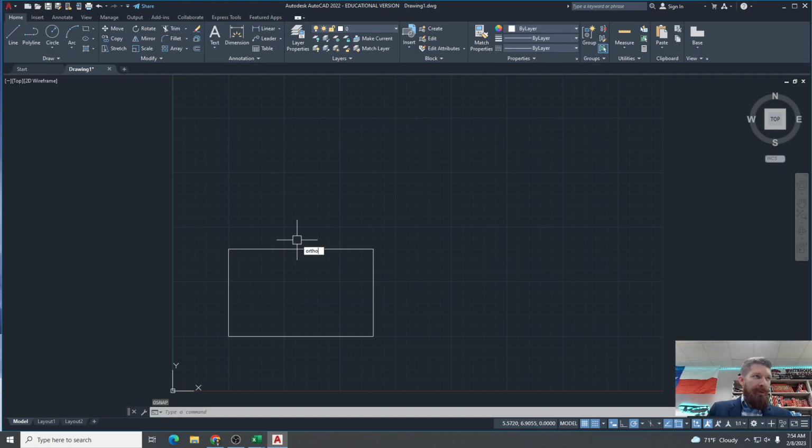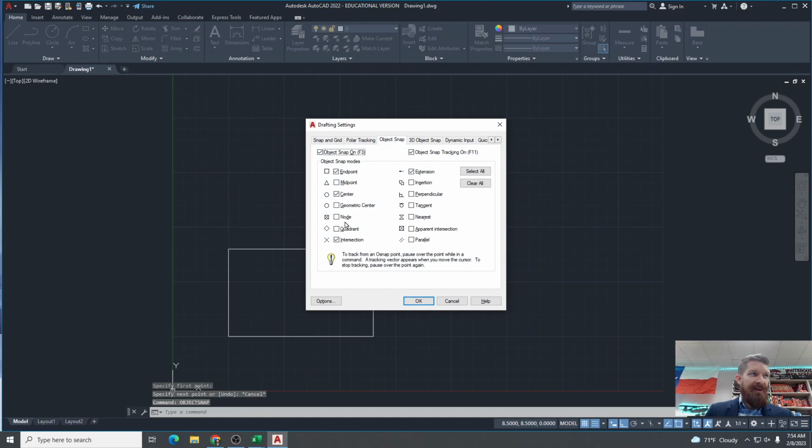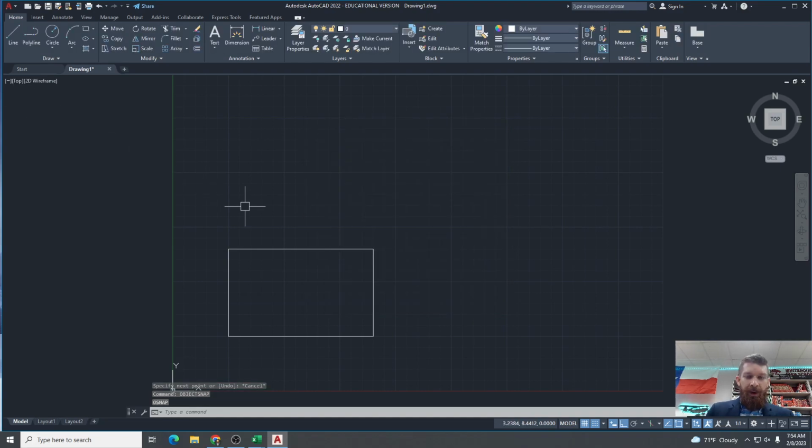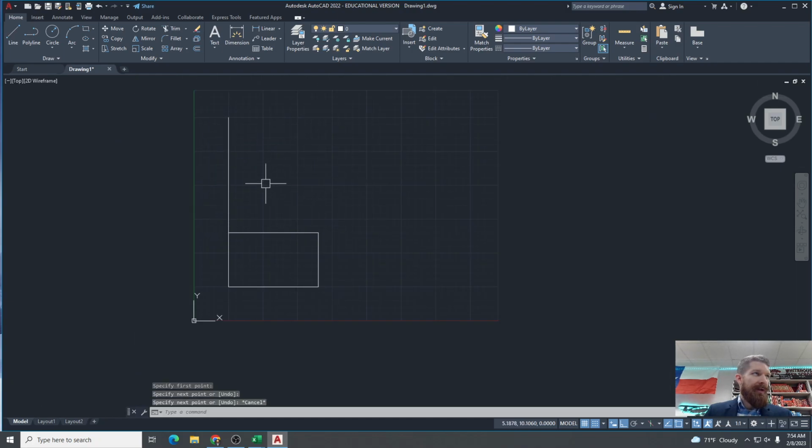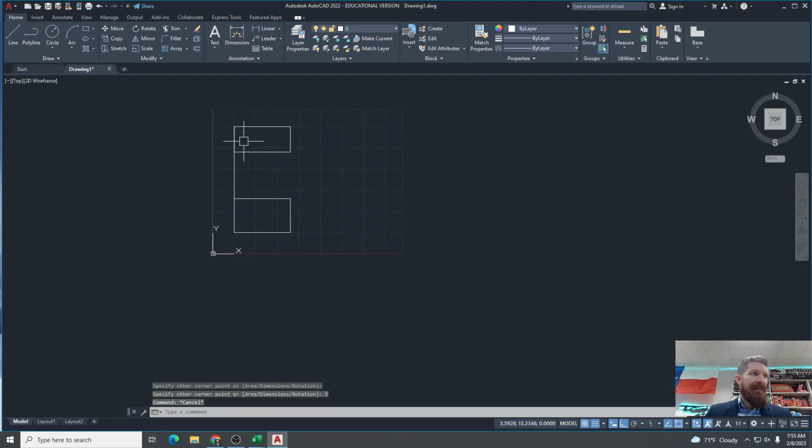So I'm going to turn on ortho. That's on. And notice when I draw a line now, I can only draw vertically or horizontally using ortho, right? Now that goes away if I've got object snap on. If I've got object snap and there's another one of these that's selected, that will override the ortho command. But I've got ortho turned on right now, so I'm going to draw a vertical, we call this a construction line, up here, right? And then I'm going to use that to guide my next point. So we'll say this is 6.5 by 3. So here's kind of my top view.